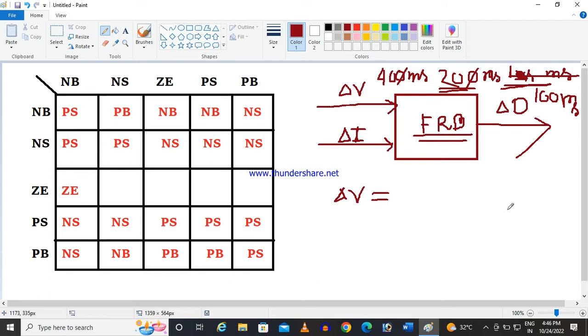What I mean to say is, to design the controller, the main aspect you should find out is you should configure the ADC, and you should see the fuzzification and the defuzzification, whatever the total time taken, your duty cycle, that means the switching frequency, at least should be greater than that. Otherwise, there will be some error.